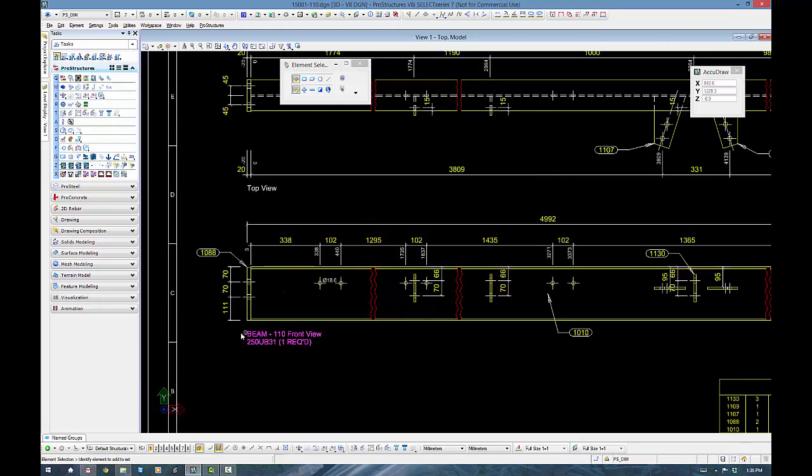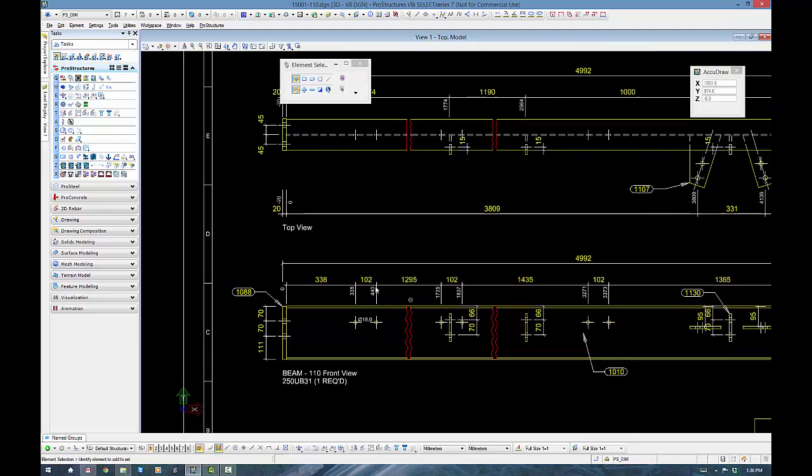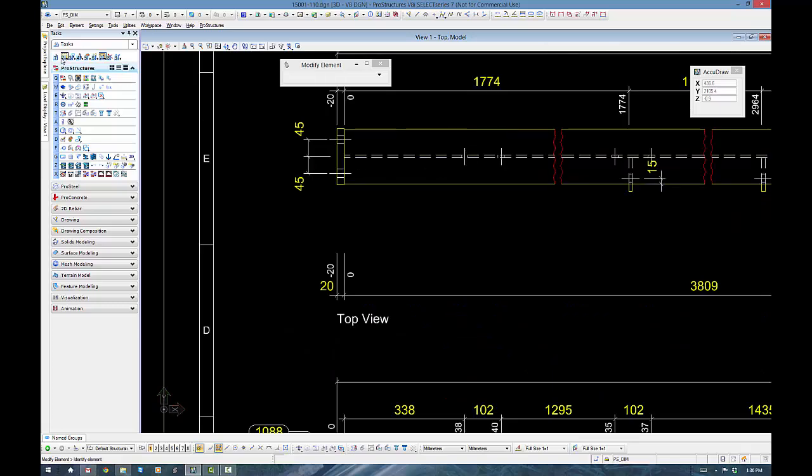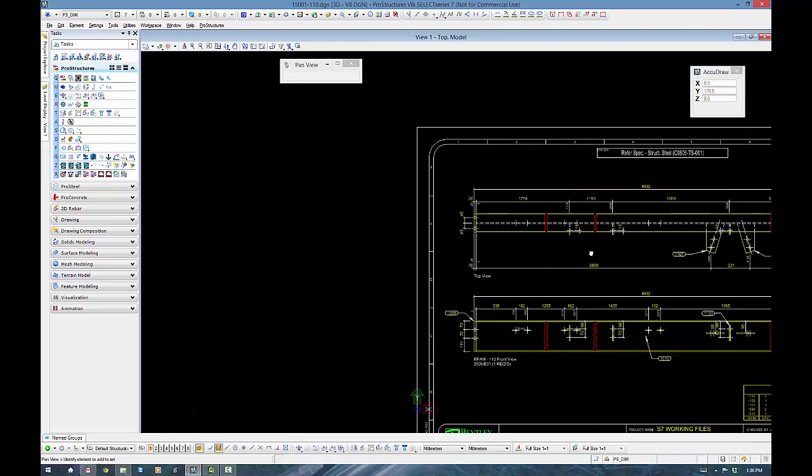Additionally, you can see that some of the extension lines don't come all the way down to the object. It's just some of the rules that have been set by dimensioning. You can just grab the end node and drag that down. And if I wanted to move this, 0, modify, which is number 7, 7.1, do that. But these guys here, if I wanted to extend those up, I'll just grab it by the little grip on the end and it'll drag around just fine.